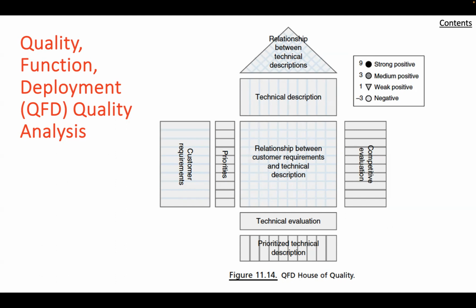So the figure that we're showing shows that it consists of 6 elements. More complex forms of the QFD House of Quality are also available, but not presented here. The basic use of the QFD is the design process, keeping design engineers, manufacturers, and marketing focused on customer requirements and priorities. It also has been used in decision-making. QFD is an excellent tool for developing design objectives that satisfy key customer priorities. It has also been used in trade studies as a method for developing selection criteria and weighting.